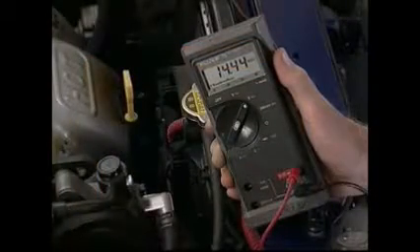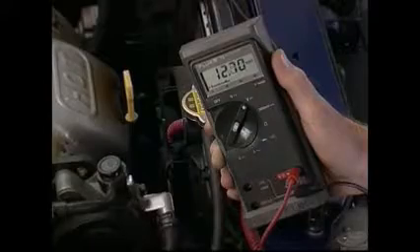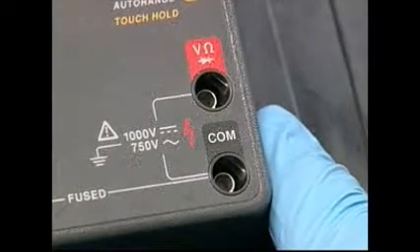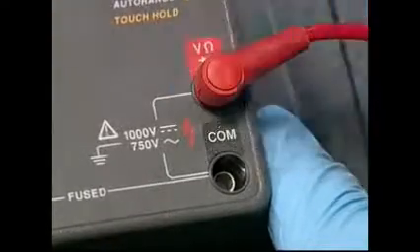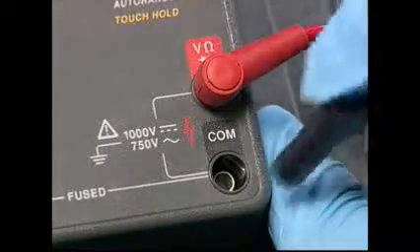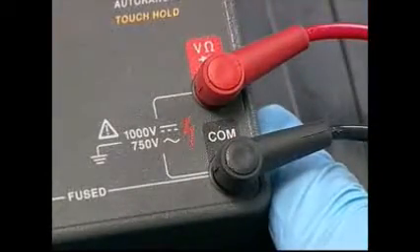With the meter set to the range of expected values, you can test for voltage in a circuit using the leads. The lead for the red probe is connected to the meter terminal marked V ohm, which is the terminal for voltage and resistance tests. The lead for the black probe is connected to the meter terminal marked COM for common.